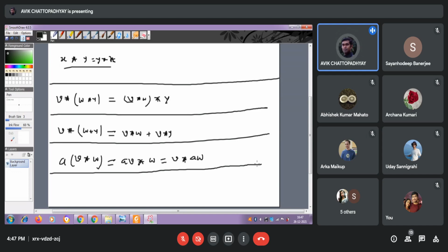So that is why, in the identity system, I think I have already drawn the picture, h[n] is equal to delta[n] for the identity system. That means whatever input you apply, you get back the same input as the output. So that is the identity system. That is basically the convolution of any signal with a delta function, which leaves that signal unchanged, so the output is exactly equal to the input.